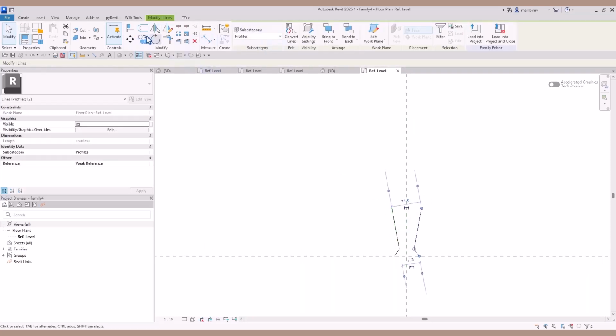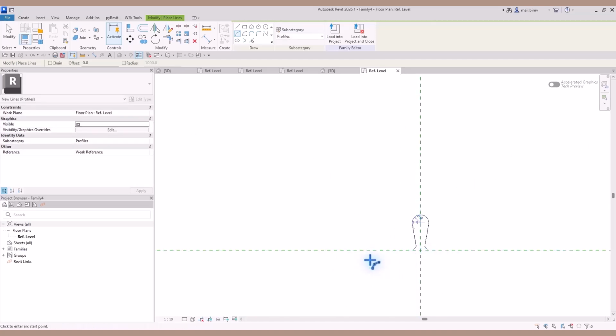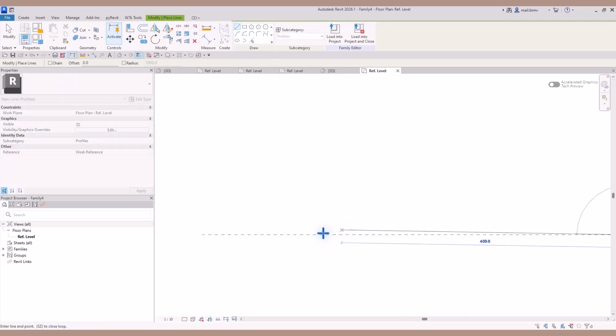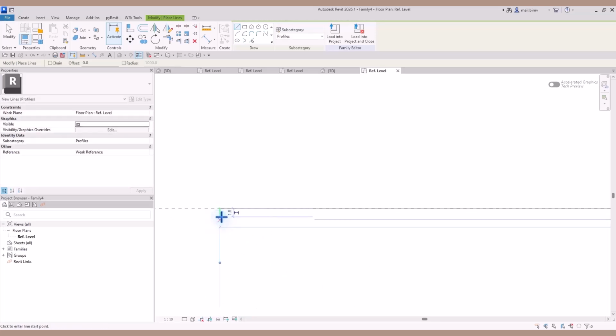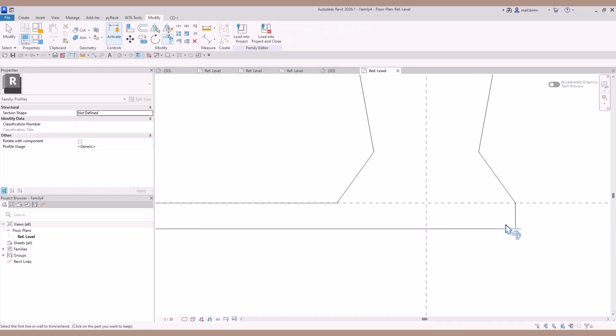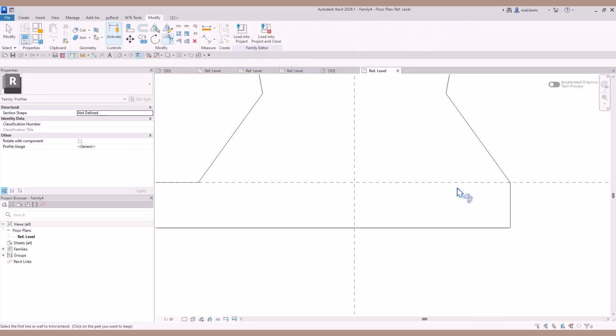Of course, I'm simplifying the profile of such a seam, but if you want to be more precise, you can do that. If you have a cut profile, you can import it and try to redraw it. But mine would be very, very simple. And yeah, the panel itself, this was the seam. Let's say it's 1.5 millimeters thick. I'm making sure that it's a closed loop. I don't have any lines that are extending too much or overlapping, so make sure it's all trimmed perfectly.